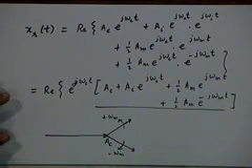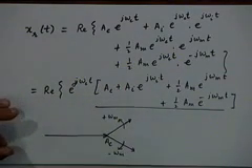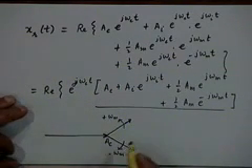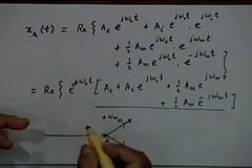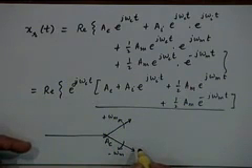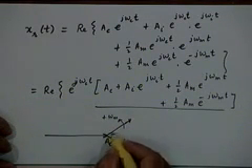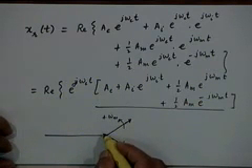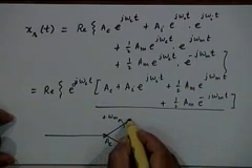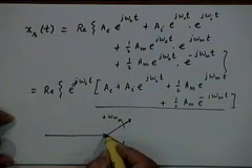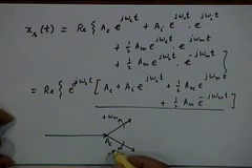This is what you will get, one phasor rotating like this, the other phasor rotating like this, right? And what you will see, the actual signal will be the resultant of all these three phasors, right? Now no matter where this rotation is, it is symmetrical with respect to the carrier phasor at any time t. If at any time t, this phasor will make an angle omega mt with respect to the carrier phasor, this phasor will make an angle minus omega mt, right?